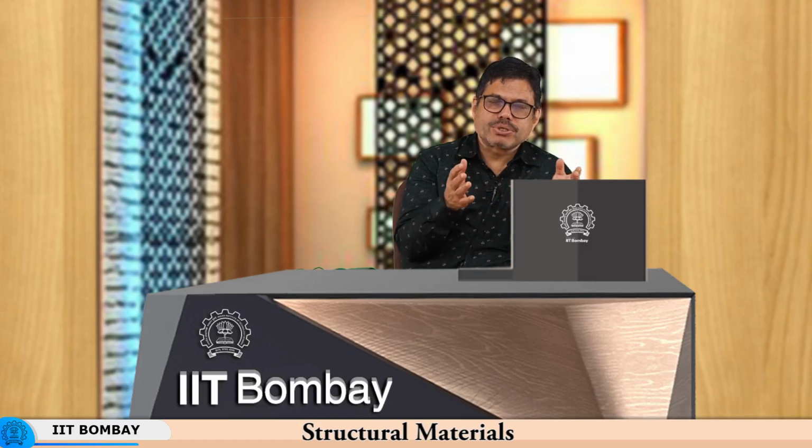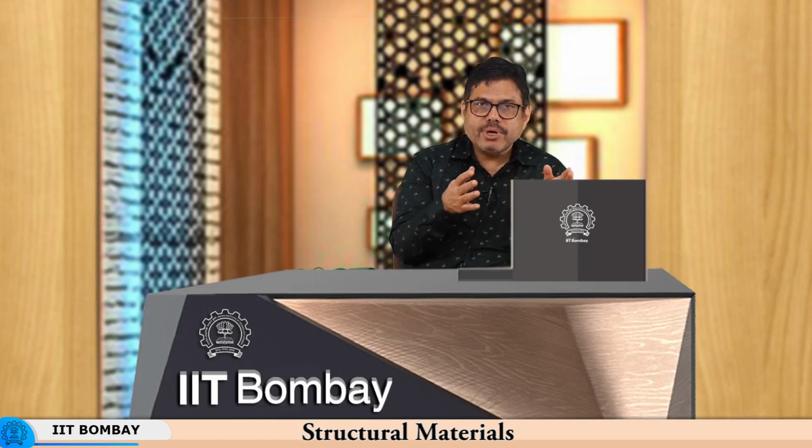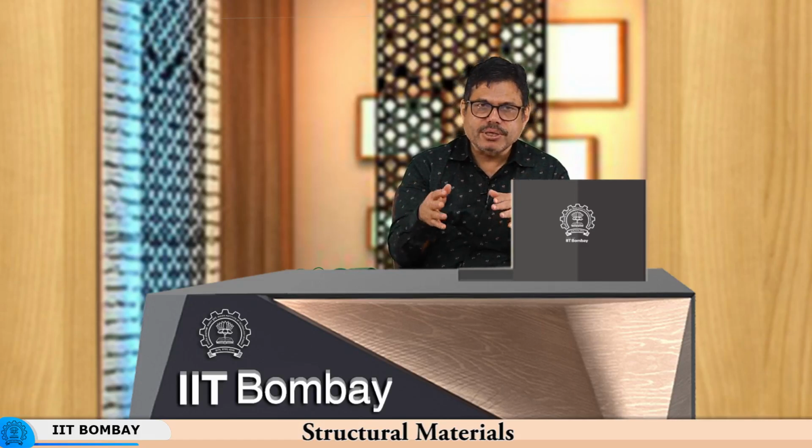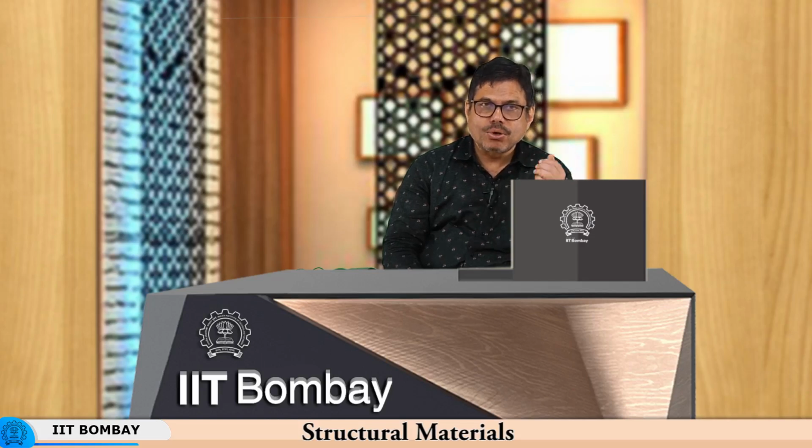Heat treatment is a process where you heat the material to a high temperature so as to get the right microstructure. Of course, merely heating will not do, you need to cool it down at a specific rate. Depending on how fast you cool it down and the temperature from which you cool it down, you get different kinds of microstructure. So, you are generating a particular microstructure to enable the chain to take a very heavy load, to take its rated load.